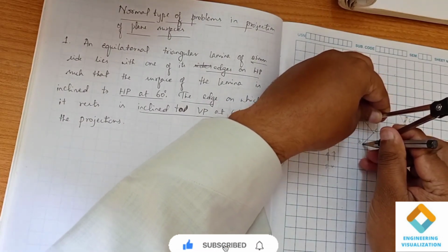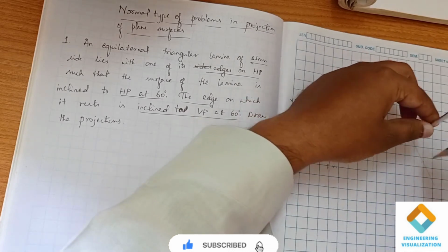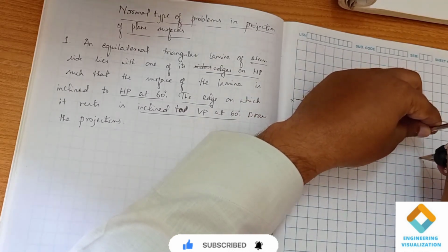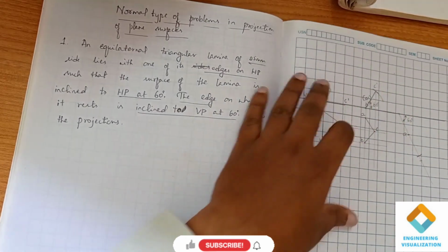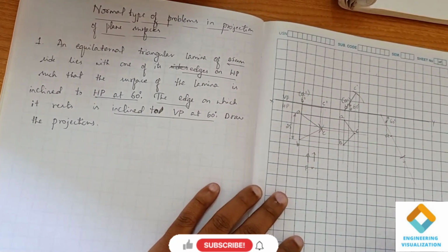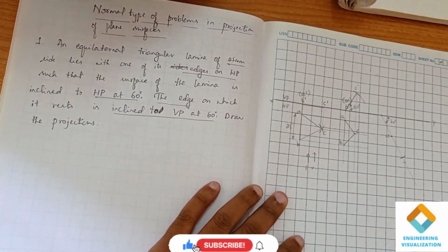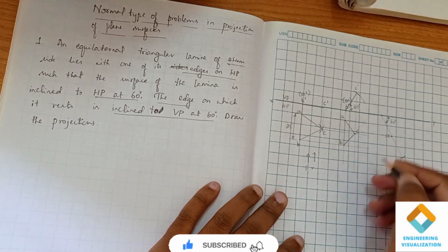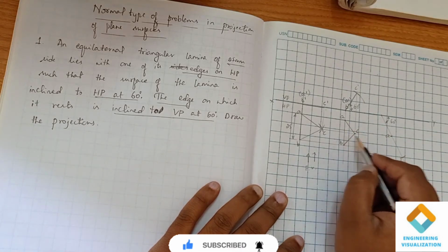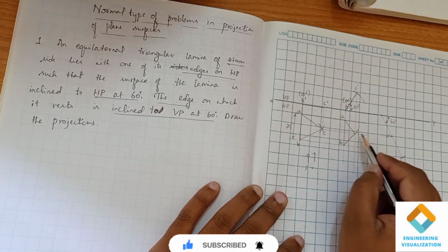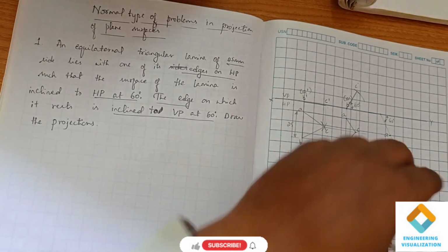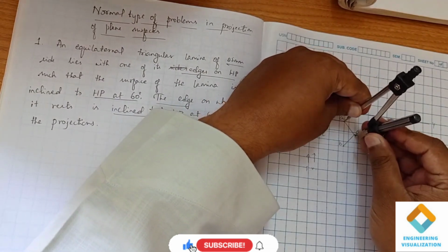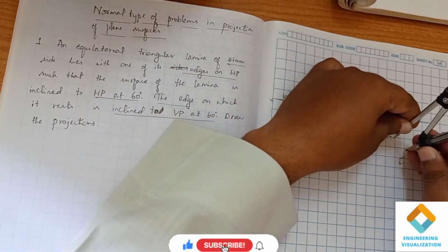We have to project the second. I have measured the length AB, so take this AB length and cut the arc. So now we got the length AB. Now we have to transfer this diagram onto this angle line. From A to C, first arc you have to cut.